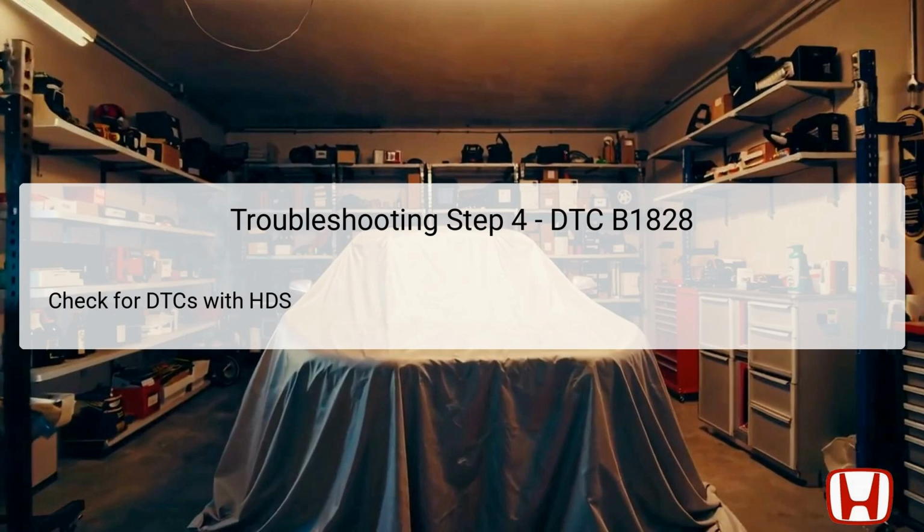This step is vital as it allows for assessment of whether the DTC B1828 reappears after performing the previous operations. If the code is indicated, this suggests that there remains a persistent issue with the recline motor or control unit.